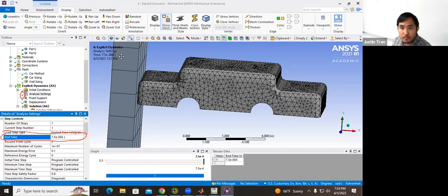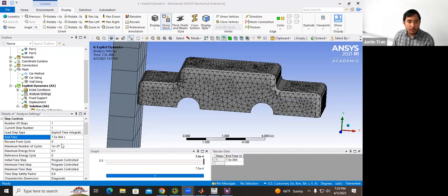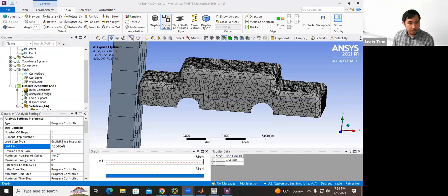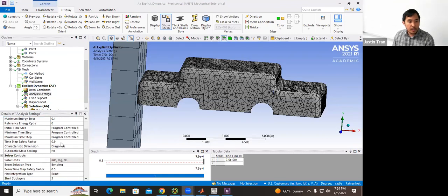All right, so that's the most important thing that we have to set, and so we have to make sure that we set that proper end time. If you remember from Monday, the other thing that's important for dynamic simulations is the time step size, right? Or in other words, the amount of time that's in between the frames of your animation.